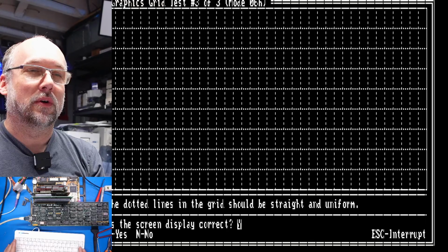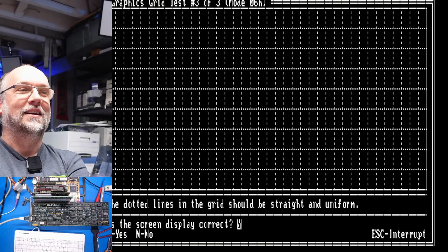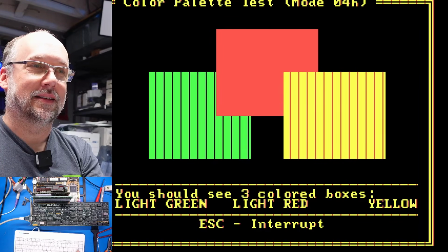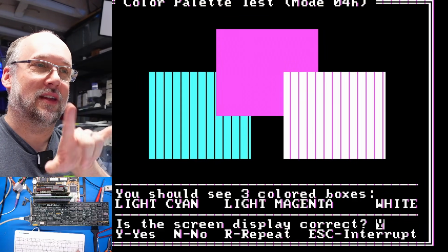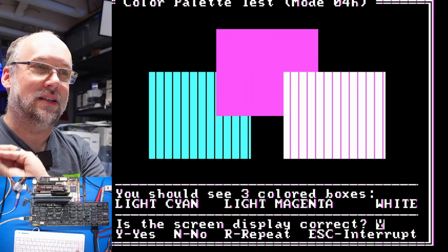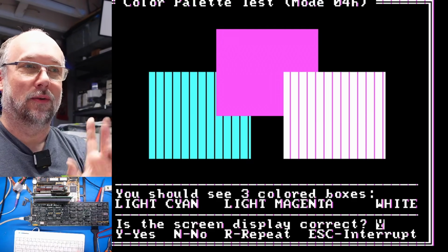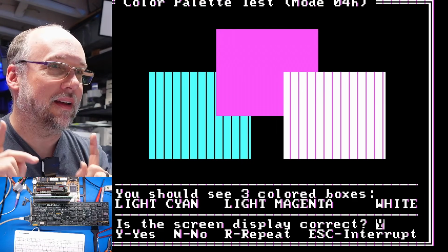That's still not quite working exactly like I would have thought. I would have assumed since it was pulled high, that we'd be seeing lines. But I guess the shift register that displays the pixels behaves differently, and it probably doesn't pull up to 5 volts internally. So I need to find another flip-flop and get that installed, and hopefully that fixes all the problems.